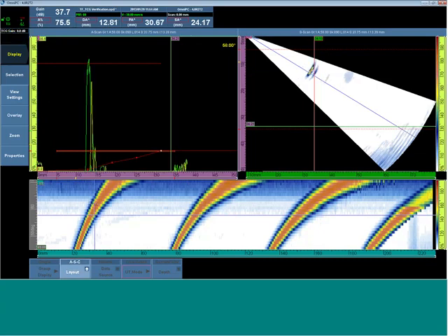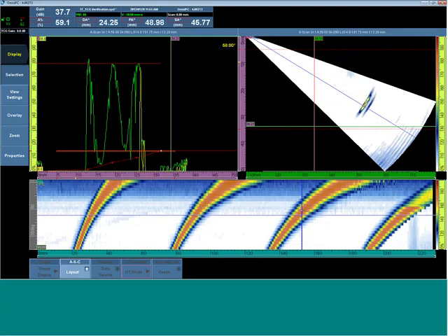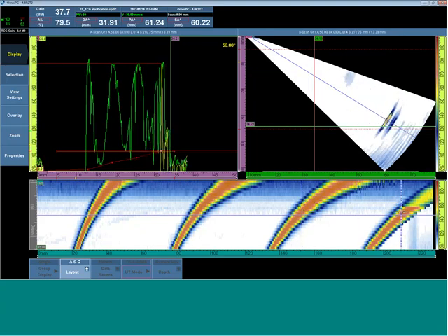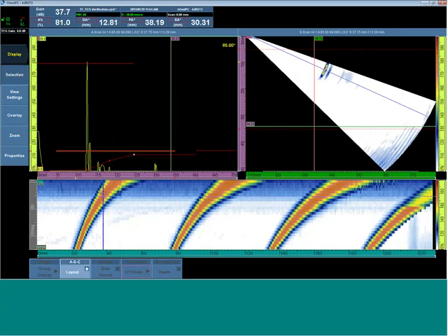If I were to drive the scanner, we can also see that any one A-scan would also have exactly the same TCG and calibration, and this is visualized in the color palette. We're going to talk about displays later, but in all of this, we're converting color to amplitude or color to position.